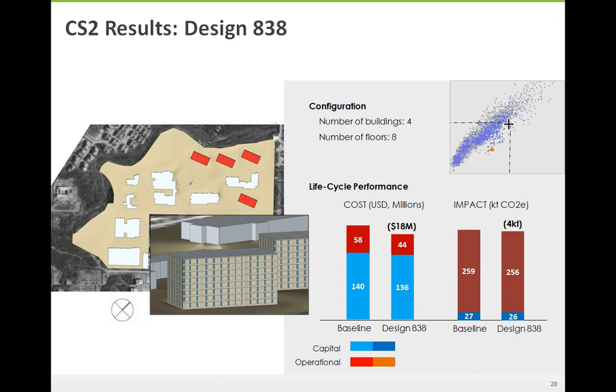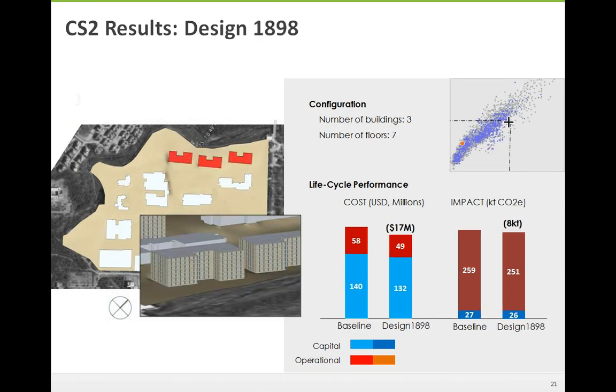So you see the buildings orientated themselves closer to that edge and further away from the edge where the blast risk was higher. So that actually enabled less panes of lower spec glass to meet the blast requirements, which led to significant cost savings, as well as operational benefits. So that's just one example. And then here are some others.